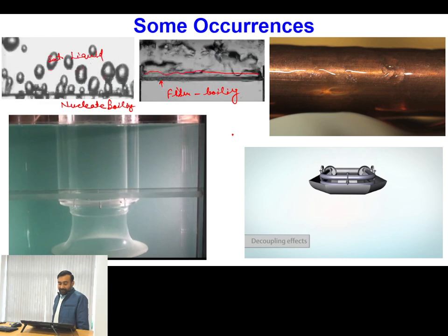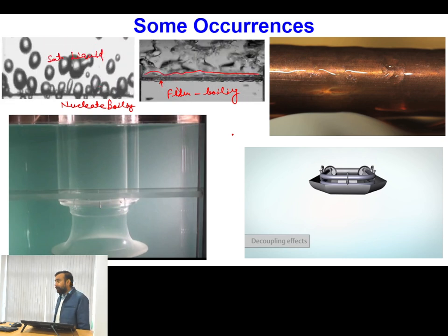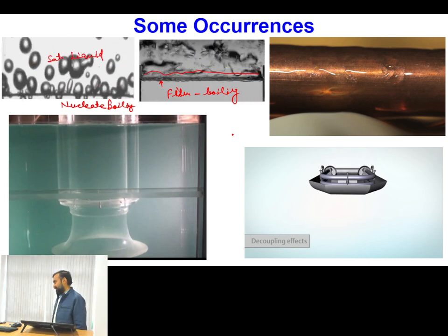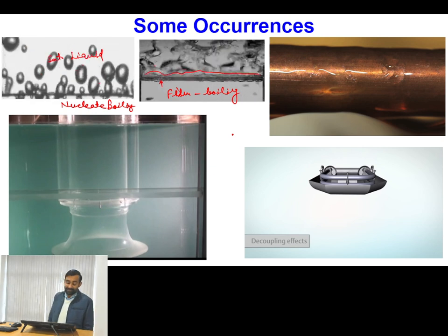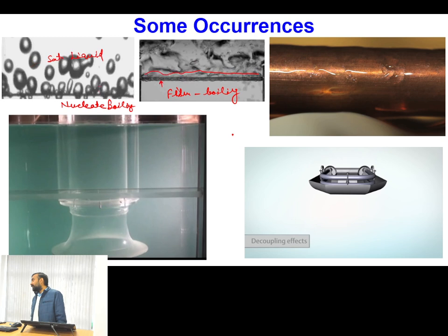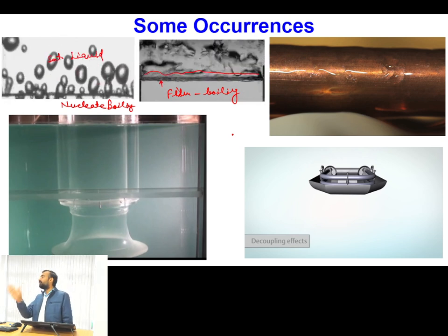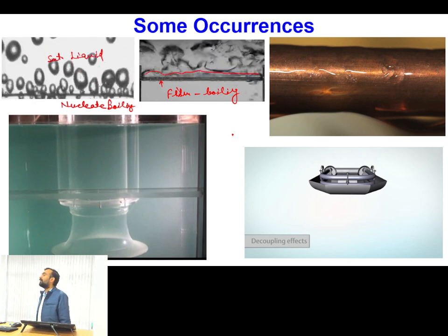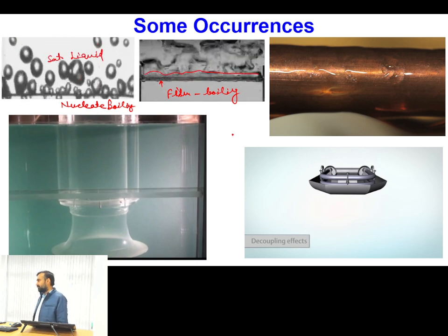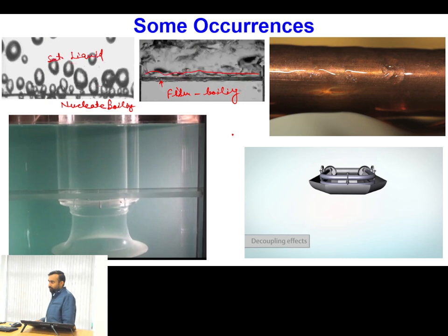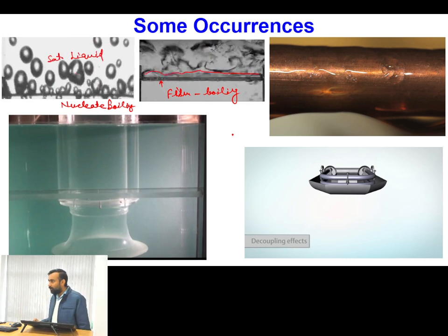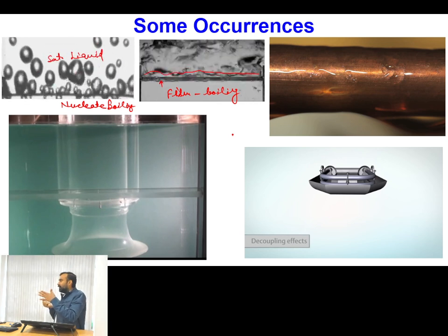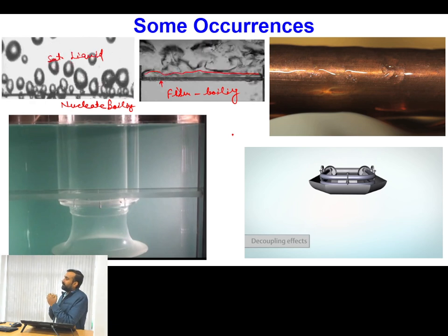Okay, and third important point is, if later on we are using this type of system in some, say, heat transfer equipment, and if there is entry of air with the liquid, and that air is contacting the surface of the solid from where this liquid was getting heat, then ultimately there will be formation of hot spots on the solid surface, because thermal conductivity of the liquid is high and thermal conductivity of gas is low. So when gas is contacting the surface, it will be taking the heat from the surface at a lower heat transfer rate, whereas liquid can take heat at a high heat transfer rate.